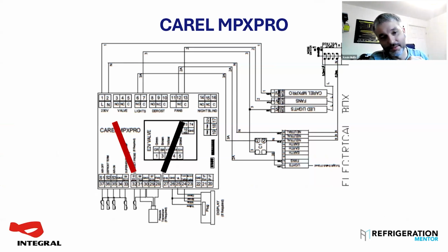They've got a whole range of transducers for sharing, which are the S range of transducers. But you only link together the grounds and the signals. You power it off one controller, which does give you an issue, obviously, if that case gets turned off for cleaning. So be aware of that. There is a parameter, which we'll talk about in a sec, that will help you out during that. But be aware, if that case gets turned off, they're going to all lose their readings.